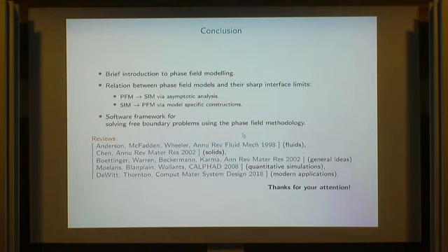But that's maybe a bit more out of the usual range. The crack propagation problem, where you don't only have one phase, but then you have the crack in between. And then you have a restriction on this crack. The crack doesn't move, but only the tip of the crack moves. So you get a constraint on the tip velocity, which then translates into a constraint on the time derivative of the phase field.